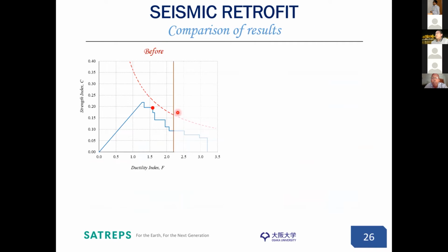So this is the performance of the building of first floor before retrofitting. And note here, we are still considering up to 2.2, not the full range of 3.2 as given by PWD manuals, because this particular building ticked off certain criteria which puts it under a possibility of exerting pull-out failure.